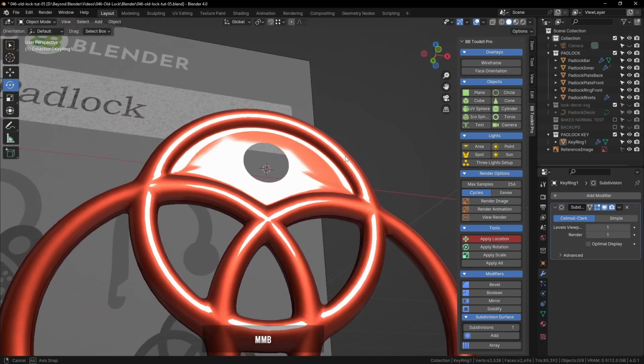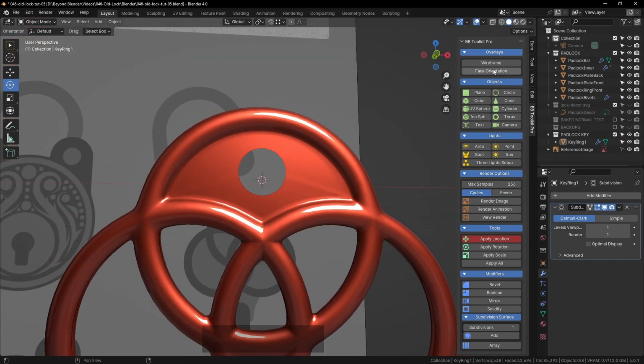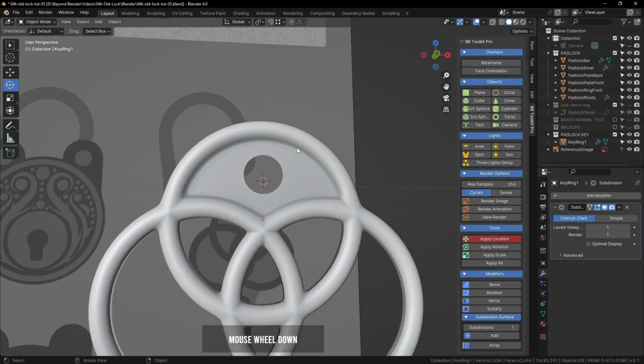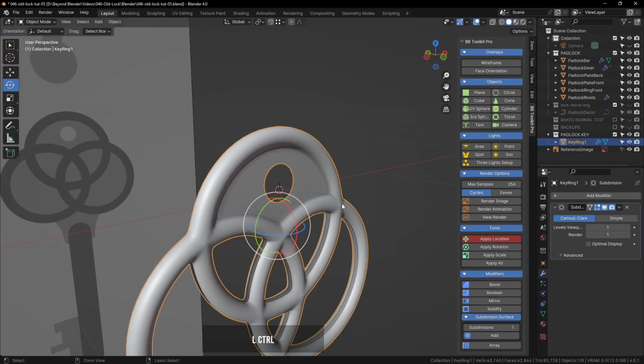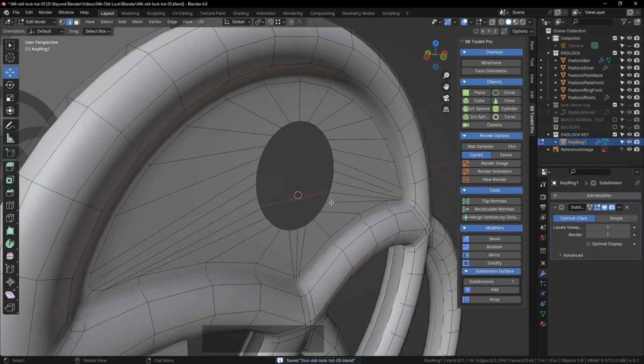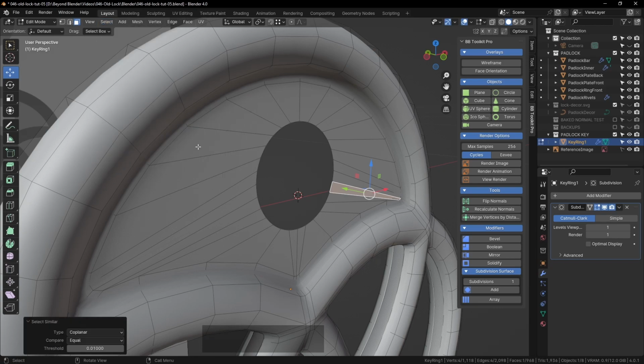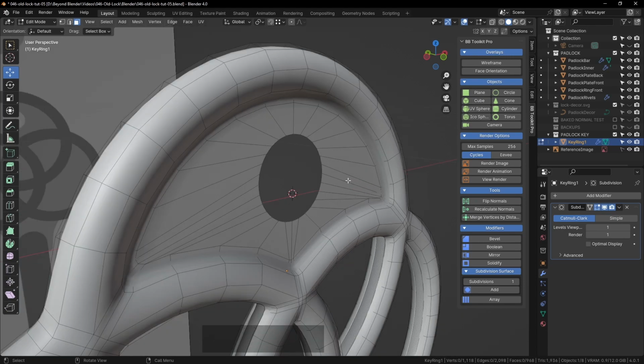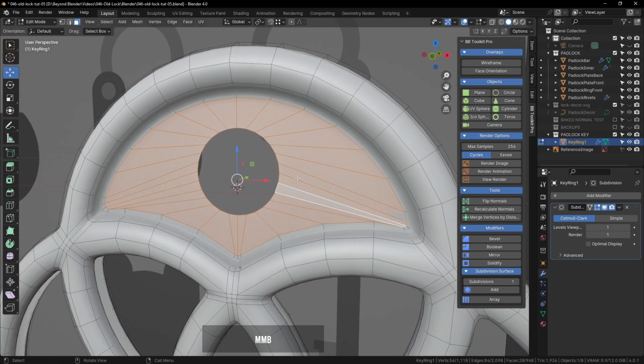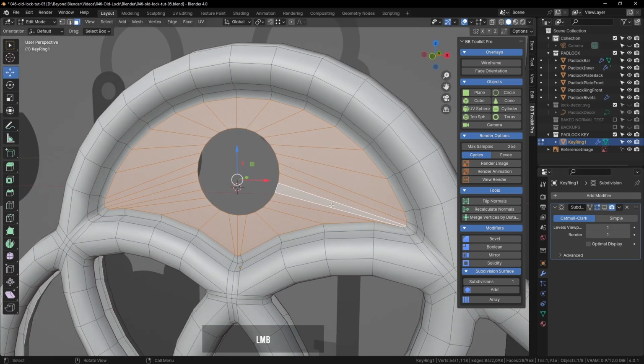And I switched over to the matcap to see how that looks in terms of shading. We still have a bit of work to do. You can see we've got some weird shading issues going across there with these polygons, these faces there. Let's try and select these with coplanar. Didn't quite work. But that's easy enough to select with the C key. That becomes your selection brush. Just paint over that and right click to escape that operation. Now we have the selection there.